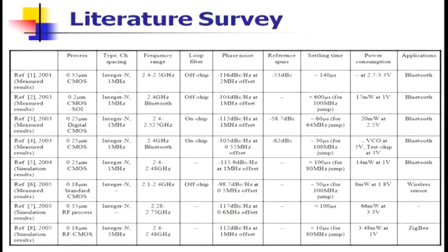The frequency synthesizer is hopping from channel 1, locking in the signal, getting the modulated signal extracted out of it, going to channel 2 like that. The same frequency synthesizer is working. Then what will be the time required for hopping? Suppose your data bit rate is 1 Mbps. So you need a settling time of at least a few microseconds.